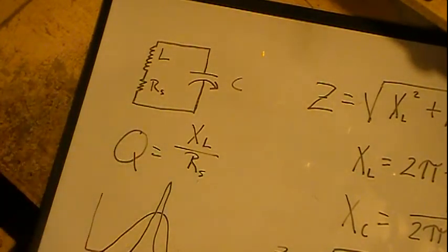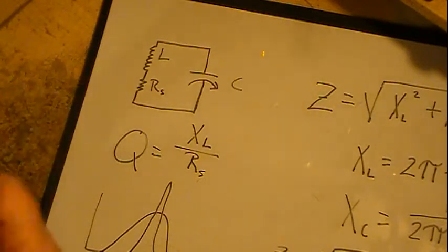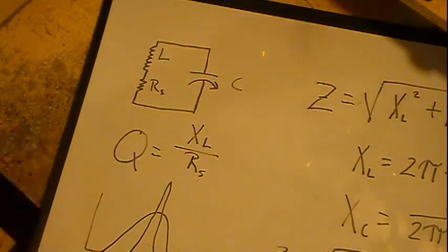It'll be a small value, because most of these coils run like 6-8 ohms. So if you were off, say you were only like 4 ohms on your coil after you got done, you could add a little 2 ohm resistor in there just to bring that Q back into something that is probably what it should have been. But that's all you've got to do, just add a series resistor in, and that takes care of it.